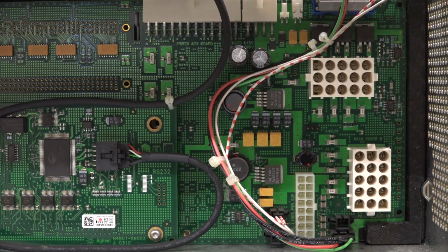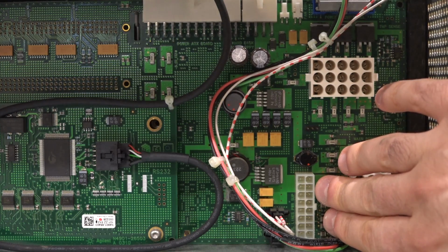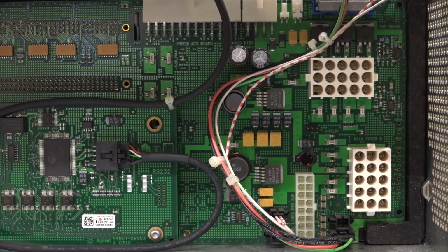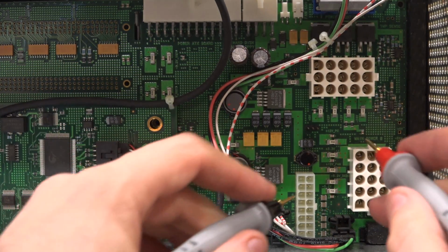We're still not 100% sure if it's the power supply. It may very well be that the control signal, for example, that's supposed to trigger the power supply to turn on is not doing what it's supposed to do, and I have no idea which wire that would even be. So we have to go and see if we can figure it out once we analyze the power supply unit itself. But nonetheless, I can go ahead and check each of these fuses individually with my multimeter.